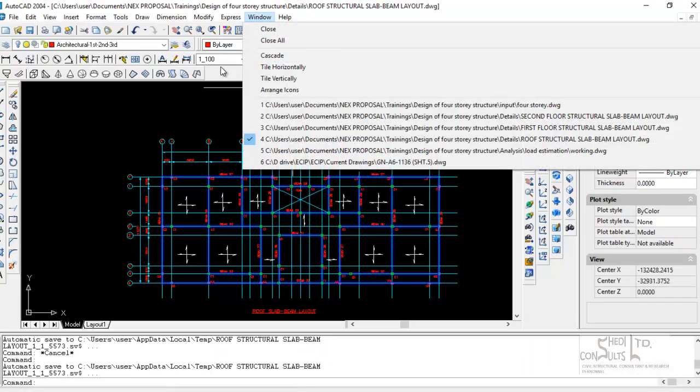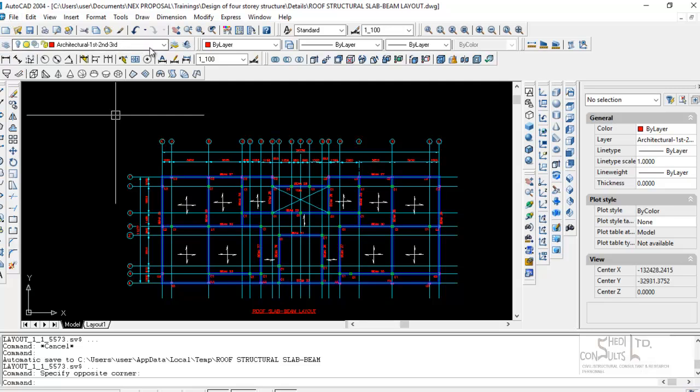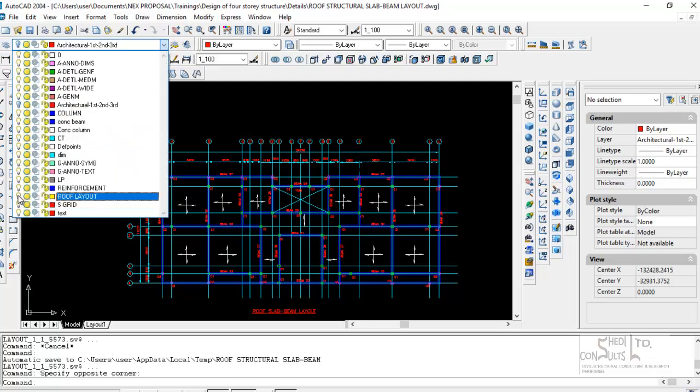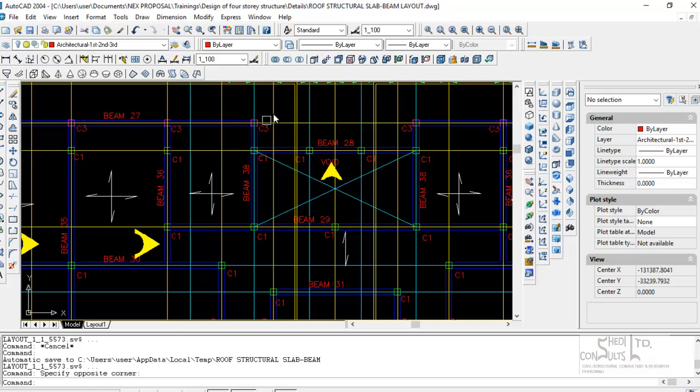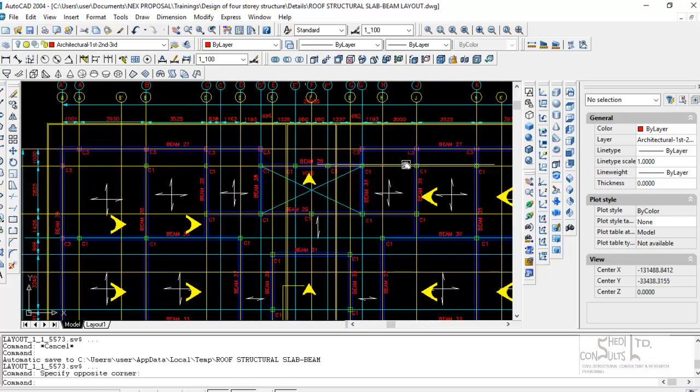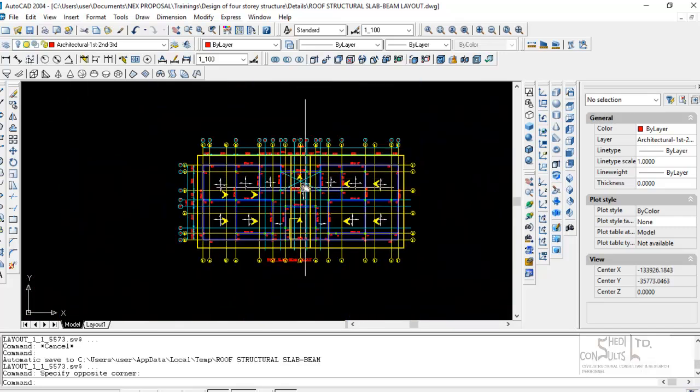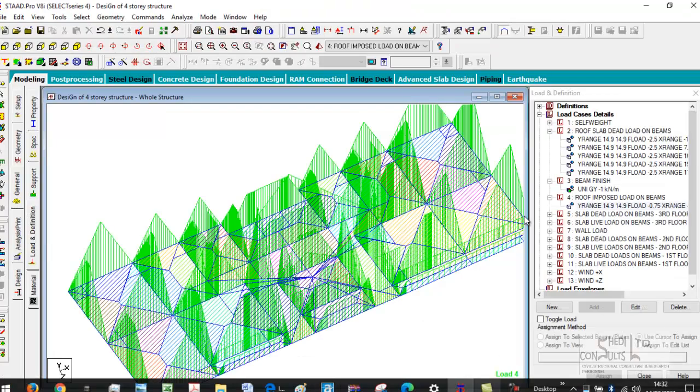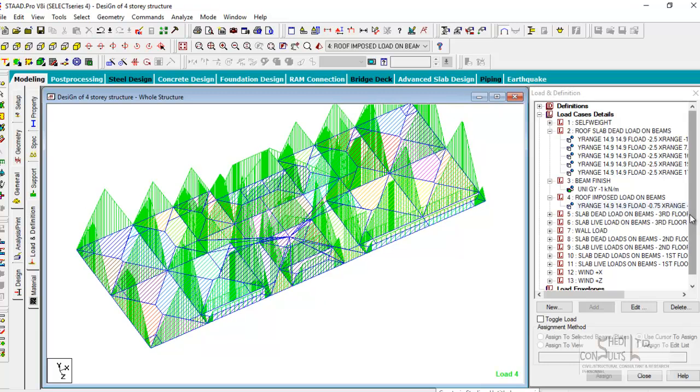Now, like we said, the architectural roof layout shows that you have roof over the void. So if there is a maintenance in future where the owner of this structure intends to maintain this roof location above the void, you would have live loading on this location, which will transfer to this beam. So the live load is correct. Okay, so our live load application is okay.